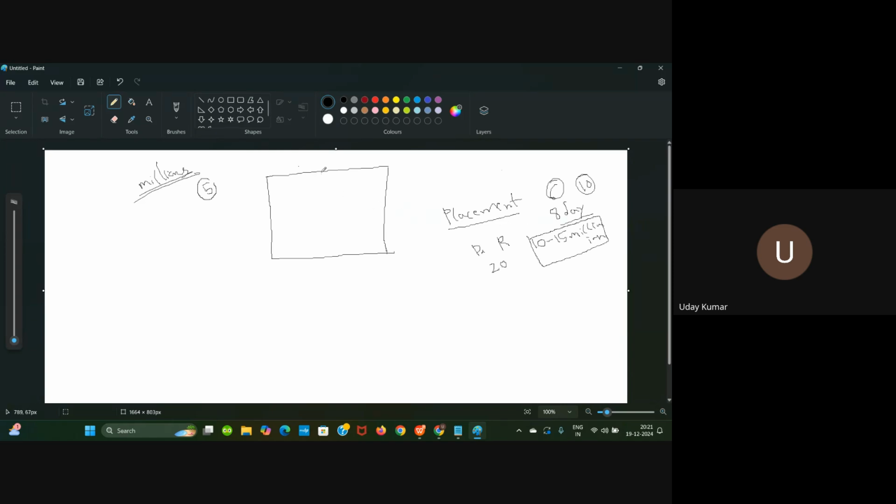So you need to break down the netlist into parts and give this part to one guy, this to another guy, this to some other guy, call them block owners. They will do the PNR in parallel, and then finally they will integrate.